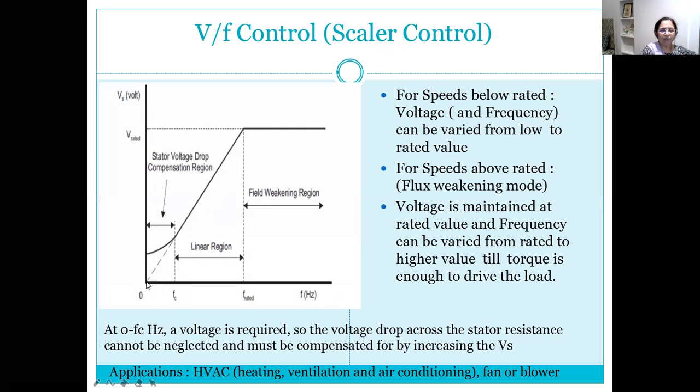Now when we operate from 0 to rated frequency, the induction motor speed will increase proportionately up to rated speed, starting from near 0 value. Okay. So the entire speed control range appears to be available, where proportionately voltage can be increased and frequency can be increased, maintaining V by F ratio constant, and we can operate in this region at practically any operating speed.